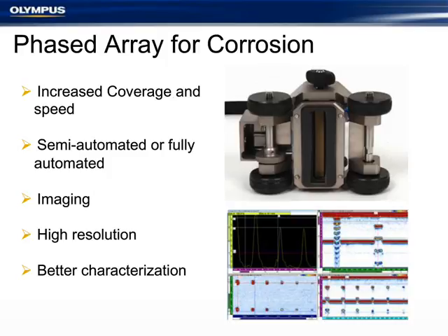So this really becomes important when we're trying to make the distinction between a corrosion cell, maybe a mid-wall anomaly, or some of those unique damage mechanisms that we can actually detect when we're looking for corrosion, like HIC and SOHIC, hydrogen-induced cracking, anything that might occur while we're doing our normal corrosion mapping. So it really gives us the ability to manipulate that data more than just a single beam and look at it for better characterization of the actual condition.